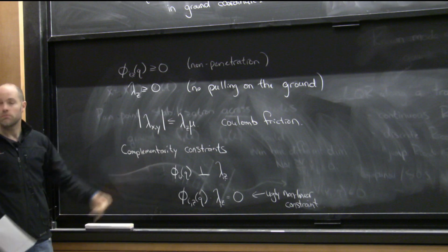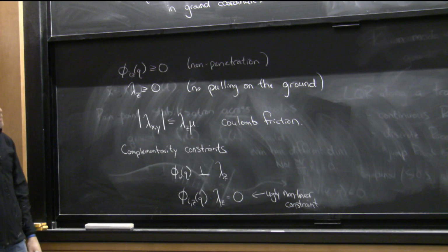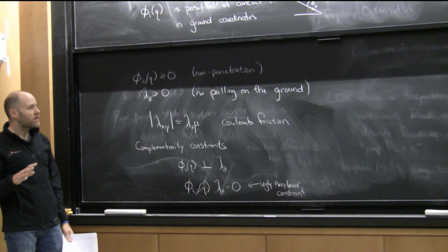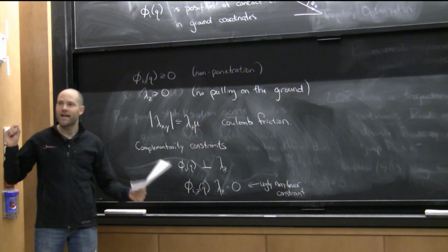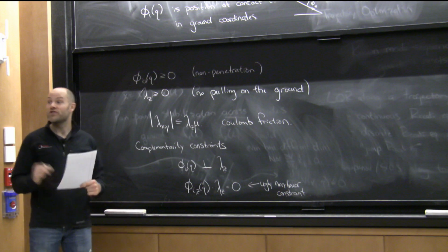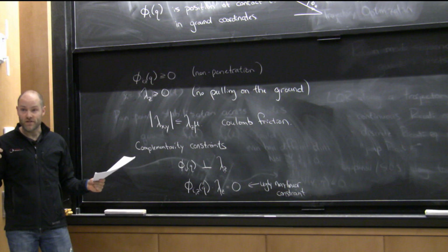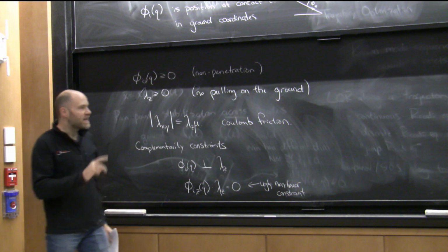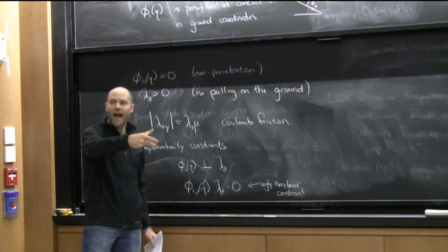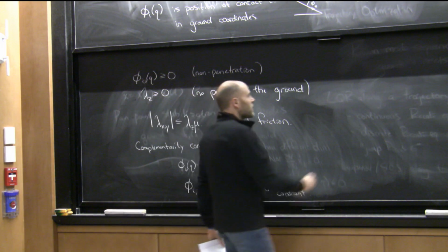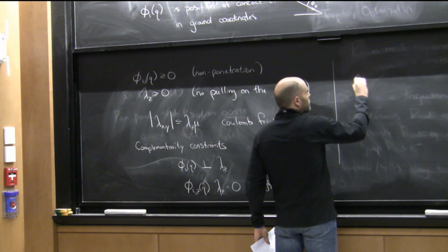If I can then simulate with this, or optimize with this, then I've got a good solution to my original equation. Okay. More importantly, by having these floating base coordinates, there is less mystery about how you connect things across different modes, right? You're always in the same coordinate system. And as the system progresses, it's basically just which constraints are active at which time. That's all that's changing. The different contact modes are different active constraints.